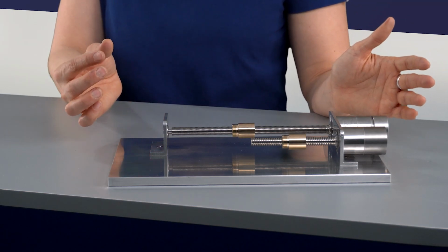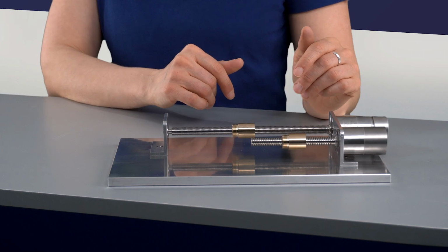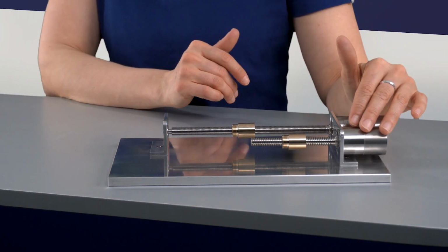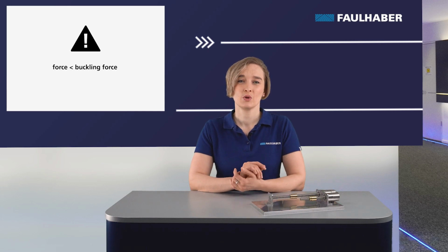The longer and thinner the screw, the lower the buckling force. With fixed single mounting, it is higher than with fixed free. Also here a safety factor is considered. This force should not be exceeded in any case. It will definitely damage the system.